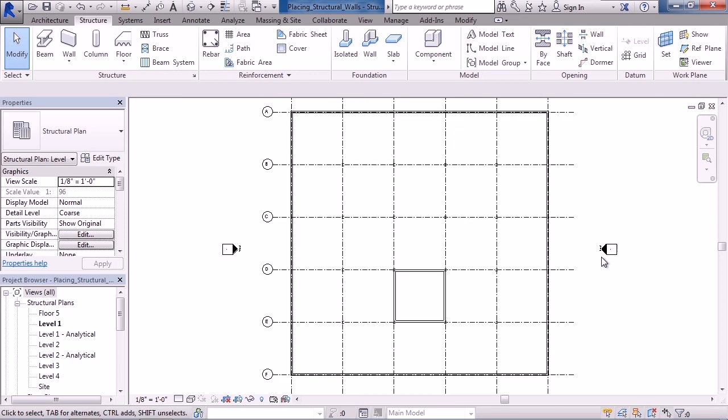You can also set the justification for the wall, meaning is it justified on its center line for the points you pick, to one face that is finished on the exterior or interior, or to a core element of a wall, such as a main block part of a wall. Then we actually drew the walls by drawing lines, but you also can draw walls by selecting lines or drawing different shapes, such as a rectangle or an arc.